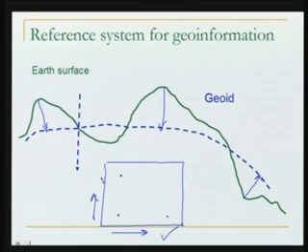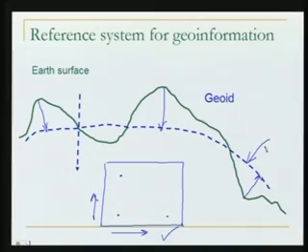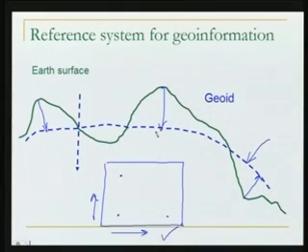Now, that was a very small example of projection, of map making, requiring a reference. But when we look at the broad earth, we want to measure geoinformation. We need a reference for that also. So we are talking here about the utility of the geoid. The geoid is an equipotential surface and we can have a feel of it. We can see it, a physical surface, as marked by the surface of a water body. Now the question is, can we use the geoid as a reference for projecting the points which are on the surface of the earth onto it?